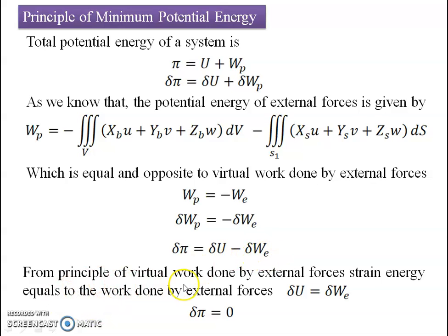But from the principle of virtual work done by external forces, the strain energy equals the work done by the external forces. The statement says that the external forces produce strain energy which equals the work done by the external forces. So the incremental strain energy dU will be exactly equal to the incremental work done dWe in case of the virtual work principle.